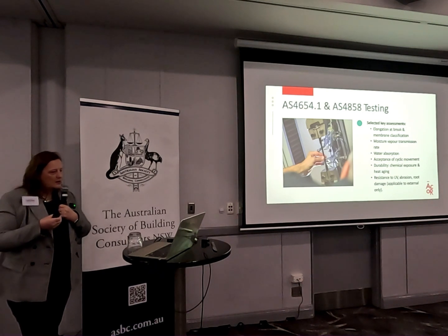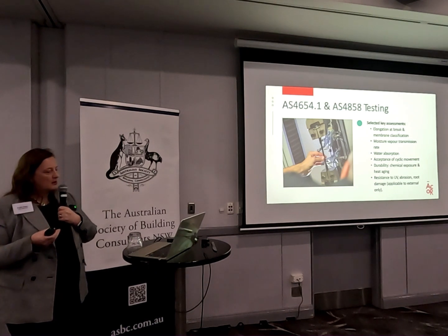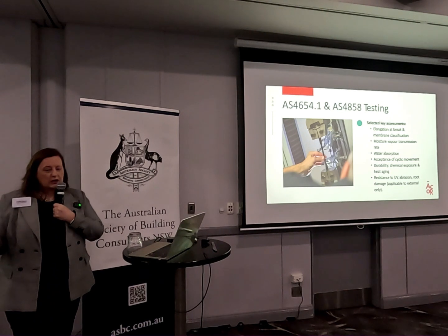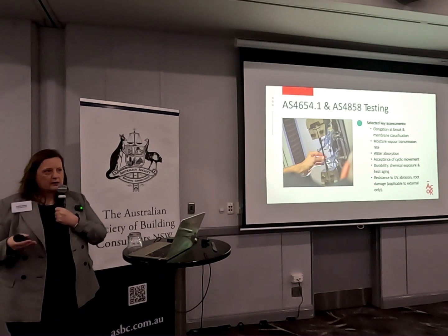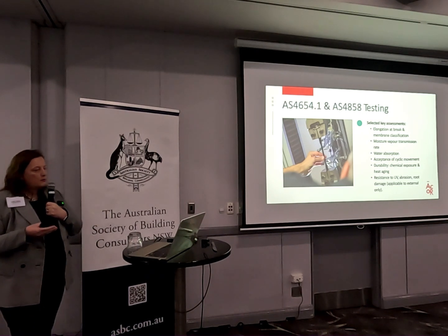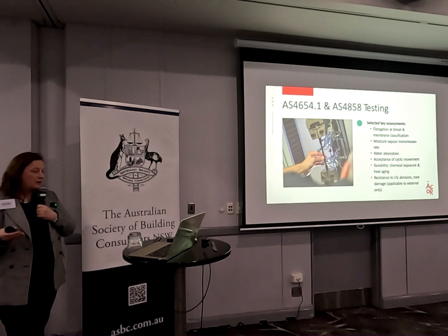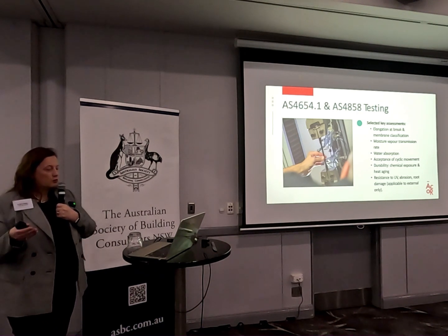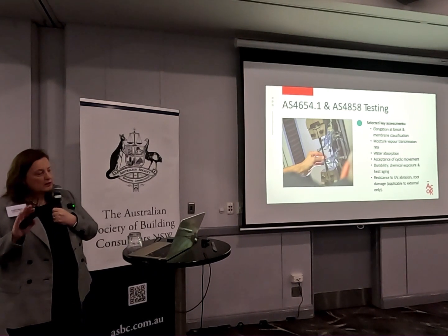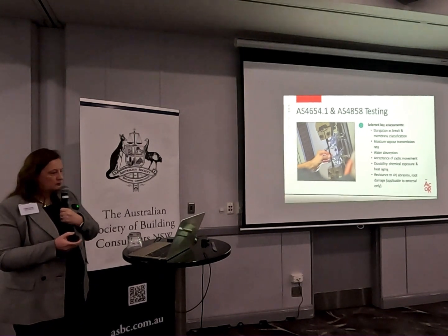The standard looks at moisture vapor testing, water absorption testing, and durability. For example, bleach and other chemicals are applied, and the membrane is exposed to them to see how it reacts. And then for the external standard, you've got resistance to UV, resistance to abrasion, and root damage. These are the 2 material standards, just to keep up with that.